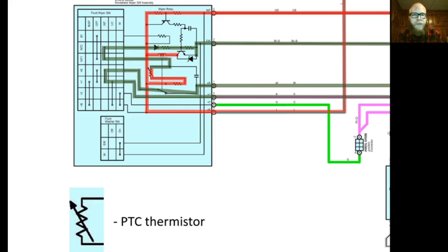So I'm stopped because my PTC thermistor got so warm that the resistance became so great that I didn't have enough current to bias this transistor, NPN on the ground side of my coil. So this transistor right now, because there's not enough voltage and current here to allow the larger current to flow, well then the relay turns off, and this is just connected to ground right now, so nothing's happening. We wait a couple seconds, right, the pause between the wipes. This cools down, and this is supplied power all the time. So this cools down enough.